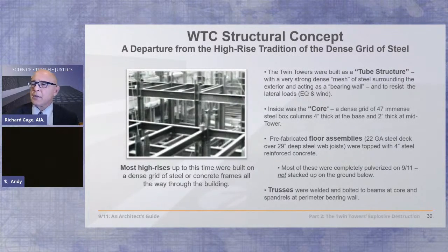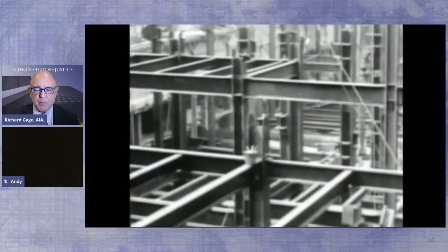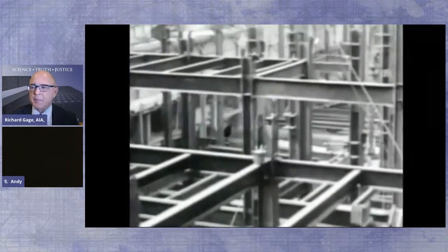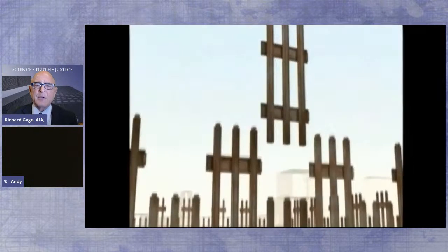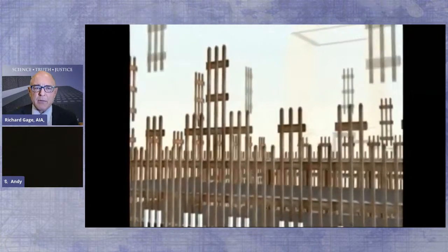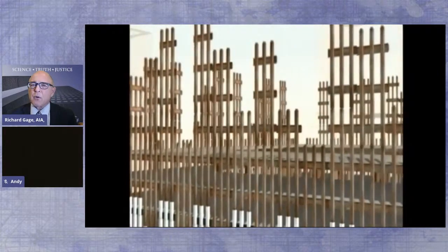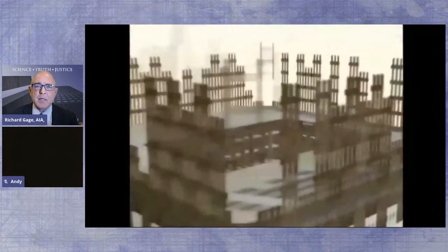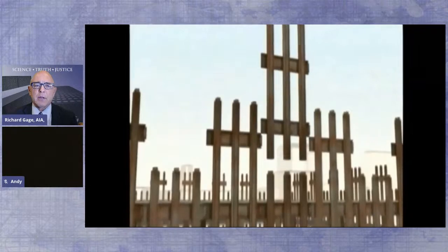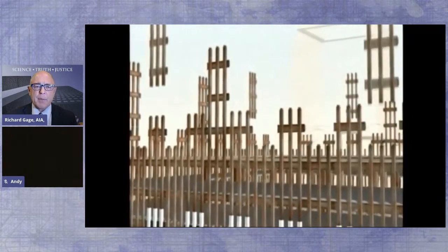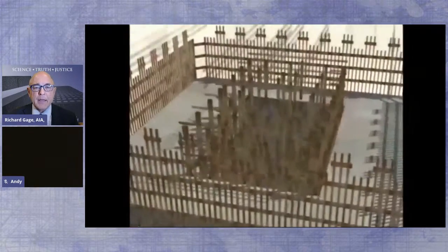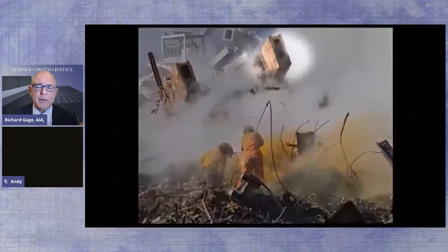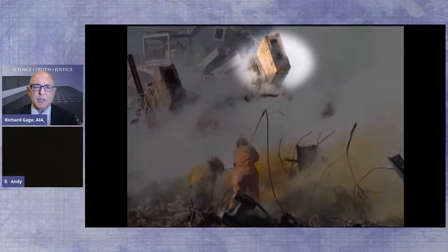And more so the structural part of this building, because up until this time, the office skyscrapers had a forest of columns, which quite really impacted the ability to lay out furniture, office space, and so forth. So with the Twin Towers, they pushed out half the columns to the outside in these 3 vertical and 3 horizontal spandrel panels welded in the shop and erected quite efficiently on the site. And in the middle, 47 massive core columns, 52 inches by 22 inches at the base, solid steel, at the mid space, 16 by 22.